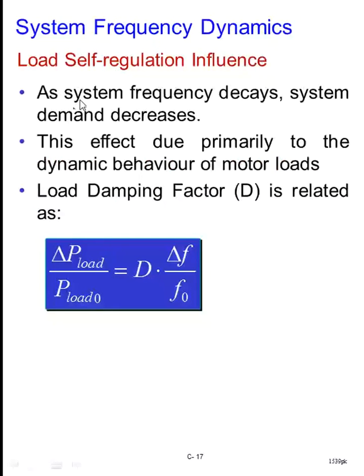So as we have the frequency decay, the system demand decreases. If you remember, we have said that the induction motors, if you have a drop in the frequency, the torque reduces, and thus the power drawn by the induction machine reduces.